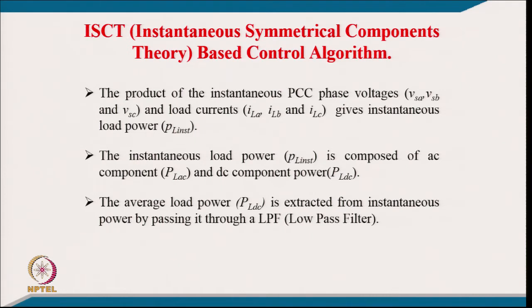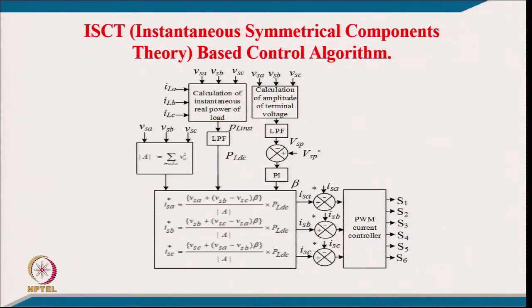Typically, the average load power is extracted from the instantaneous power by passing it through a low pass filter. So, we can get the fundamental active power consumed by the load. Well, this is the block diagram of this instantaneous symmetrical component theory based control.